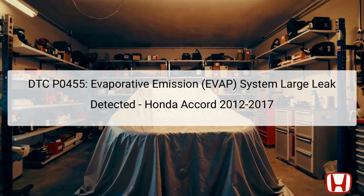This method relies on a fuel tank pressure sensor to monitor pressure variations in the tank when the engine is off. Components involved include the EVAP canister, which stores fuel vapors, the purge valve, which controls vapor flow, and the fuel tank pressure sensor. If any of these components fail or are malfunctioning, it can trigger the P0455 code. Understanding the functioning and interaction of these components is essential for effective troubleshooting.